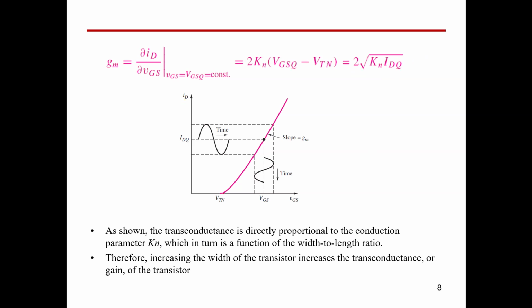You remember that, guys, we identified the value of V threshold in our lab by applying different values of VGS and detecting the first current increase. Okay, so we said that this volt is nothing but the V threshold, and the waveform we got in the lab was the same as this one. So this is the characteristic of ID versus VGS.